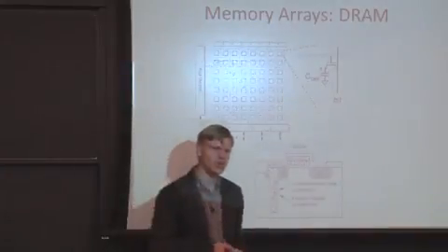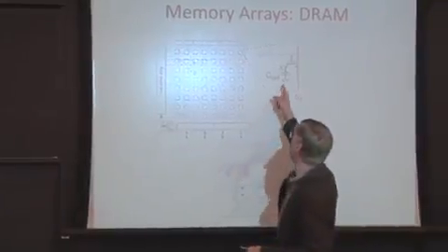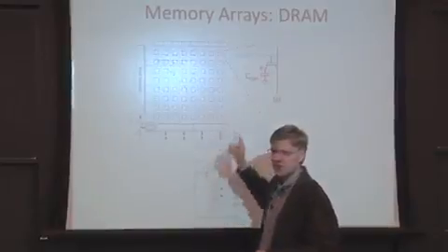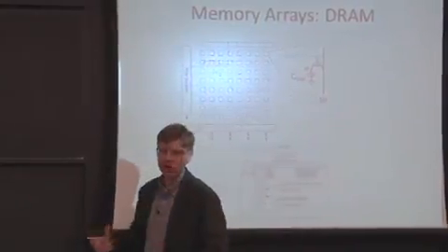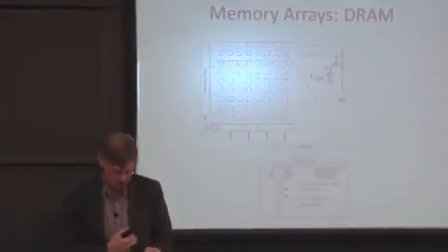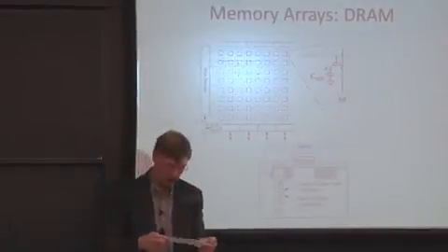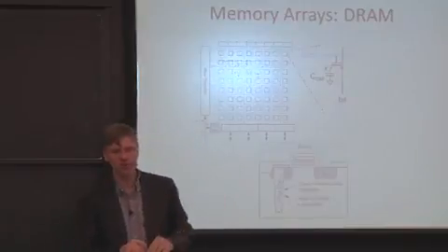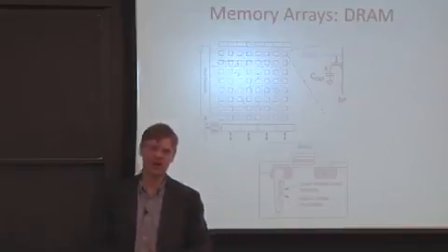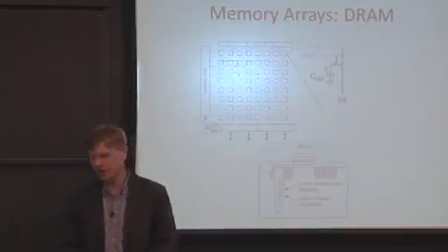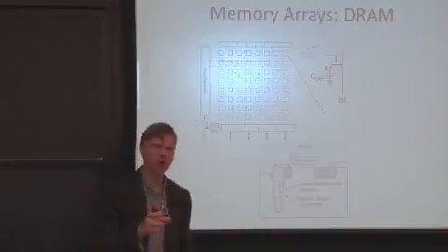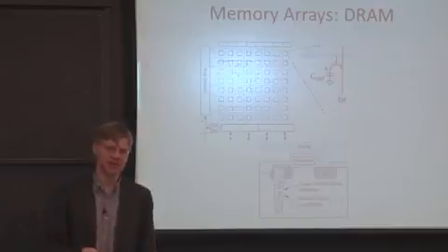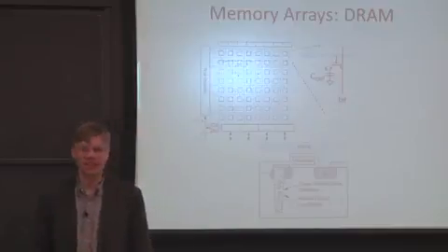Well, one of the major problems is that you're going to end up having this capacitor discharged and charged. And capacitors, as you may recall, don't always store their charge that well. They might slowly lose that charge over time. What this turns out to mean is that you're actually going to have to refresh the DRAM. So you might have heard of DRAM refresh, but typically, in a modern day computer, your DRAM will only hold the data for maybe a few seconds. It used to be that it only held it for a few milliseconds.